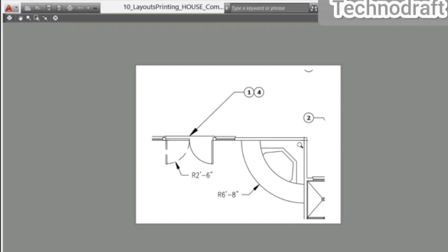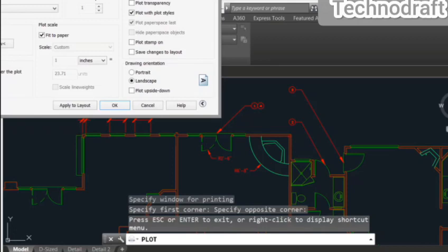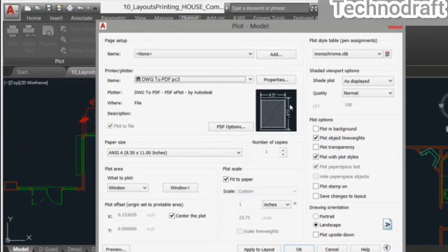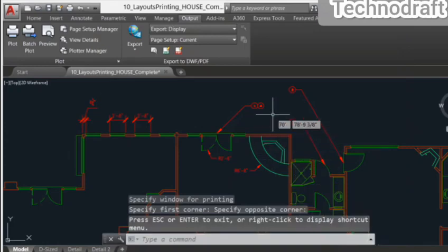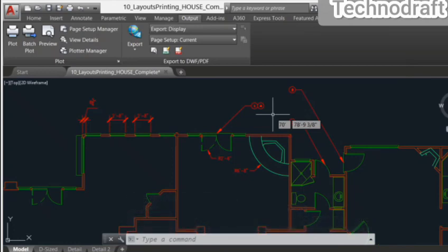That way I get that particular excerpt from the drawing, so I can use it later perhaps when I go on site to mark up some dimensions. So again I will right click, exit, there is the dialog box back again like so, and I will just cancel that now for purposes of training rather than plotting. So that's how you can utilize that window command to make your life easier to get excerpts of your model or your design, so that you can work with them perhaps on site or factory floor.